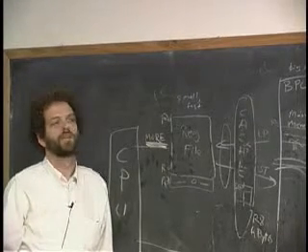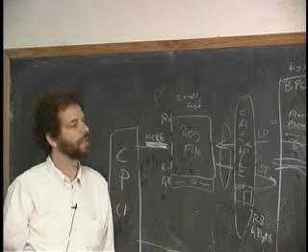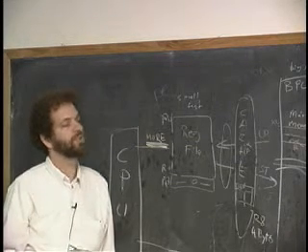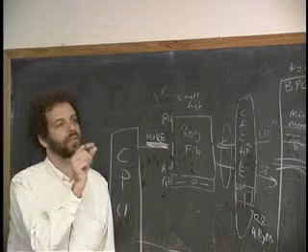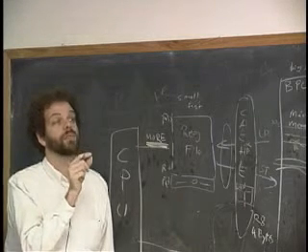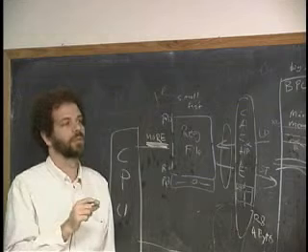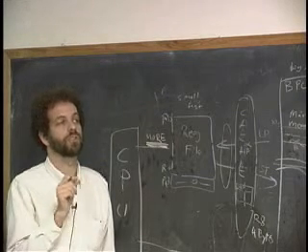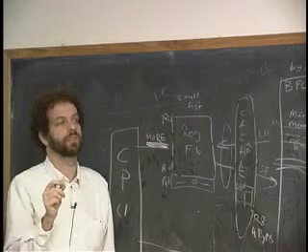They're the same type of RAM. No, there are two reasons. One is that they have less total bits. Two is that the size of the bit on the chip is bigger. There's more energy per bit. Remember that the less energy per bit, the slower, the longer it takes to figure out was it a 0 or was it a 1.